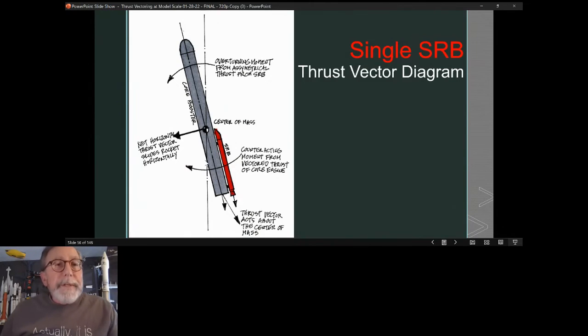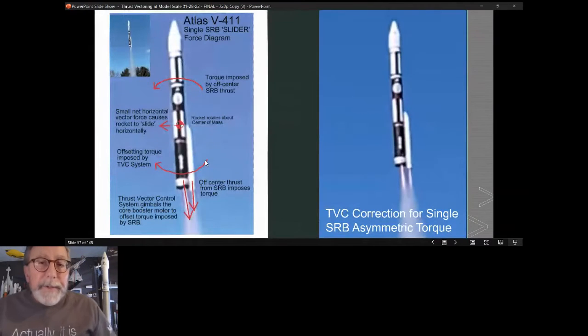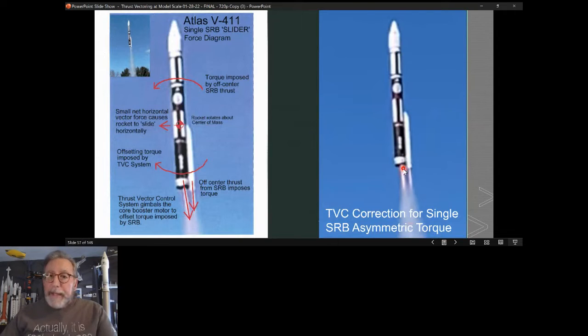And here you can see, this is a photo of one of the boilerplate rockets, and you can clearly see that it is angled this way. The BPS thrust vector system has 5 degrees maximum. And when you look at the flight data, about the first half second or so, it's all the way over at full 5 degrees.